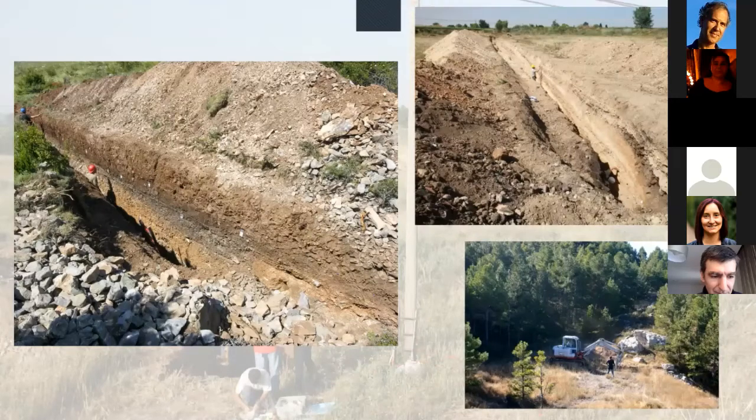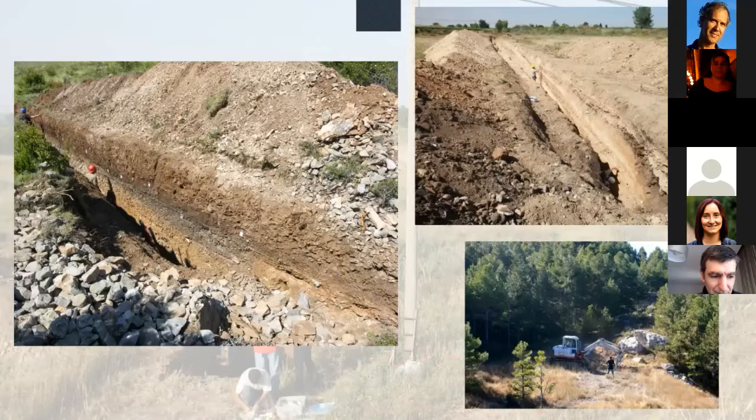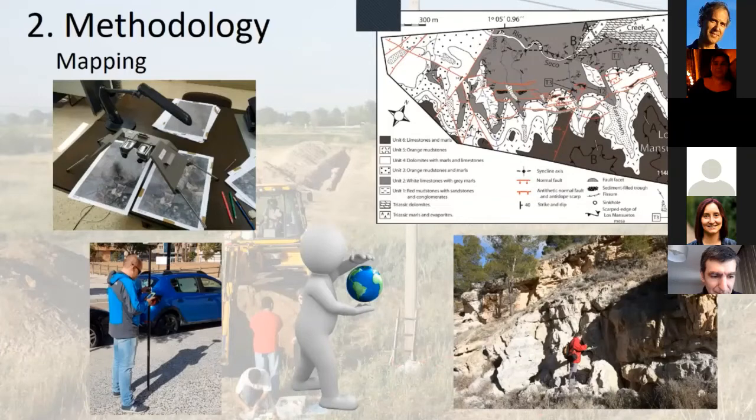And practically null in case of structures related to evaporite dissolution. It should be noted that all of the works carried out in this type of structures have been made by our research group. The success of the trenching technique is highly dependent on the correct location of the trench. Because of this, it's essential to carry out detailed geological and geomorphological maps in order to understand the structure distribution.